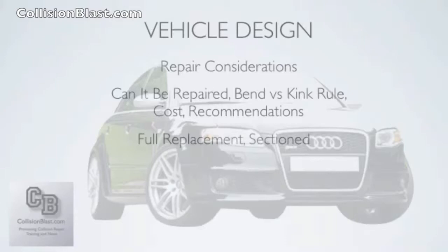There's also the bend versus kink rule. If it's bent a little bit, you can repair it. If it's kinked, if it's got a real sharp bend and may even have cracks and tears in it, that's when you're going to want to go ahead and replace. But still, that rule falls under the first one. If it can't be replaced, of course, it's going to have to be repaired.